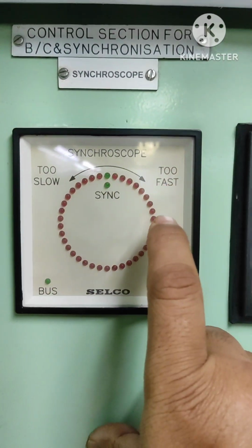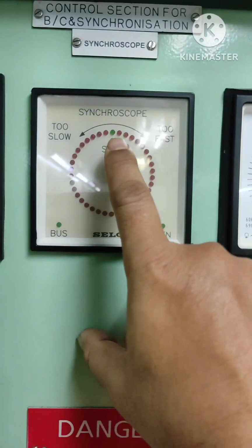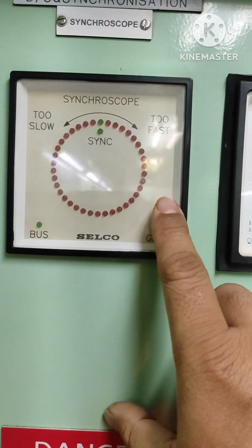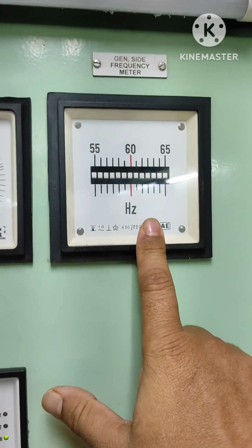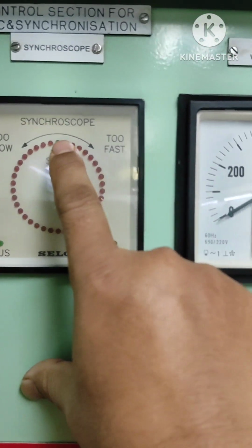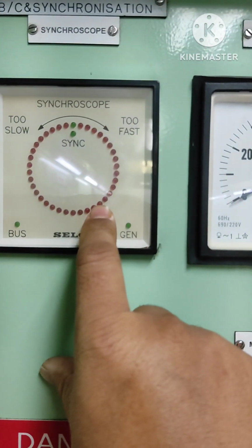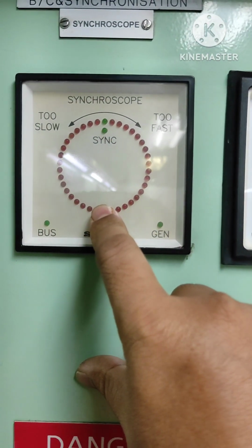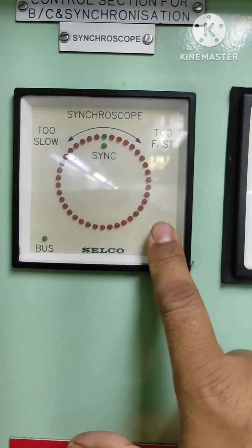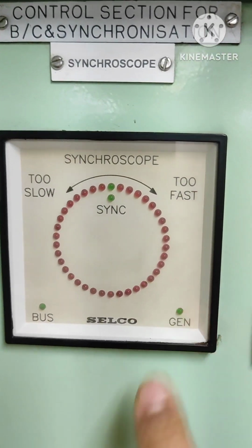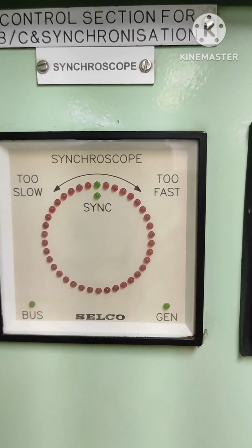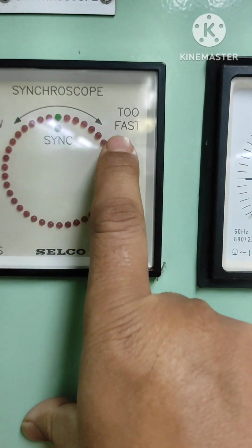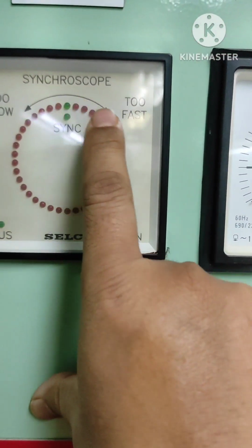These are the LEDs which will glow and run either in this direction or in this direction, depending on the condition of the incoming machine's frequency. If the incoming machine frequency is fast, it rotates in this direction. If the incoming machine speed is slow, it runs in this direction. So basically this shows the status or condition of the incoming machine with respect to the connected machine. As I said before, let's say it is turning in this clockwise direction, indicating that the incoming machine